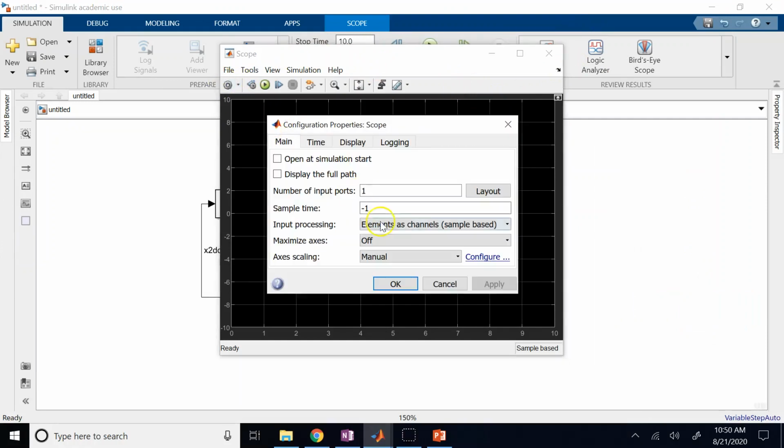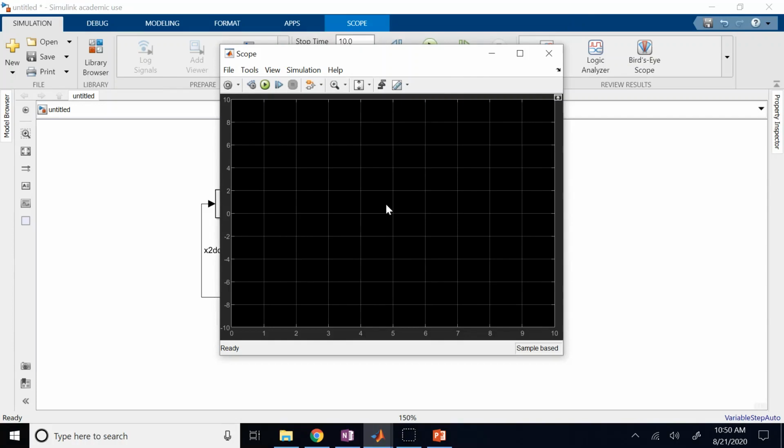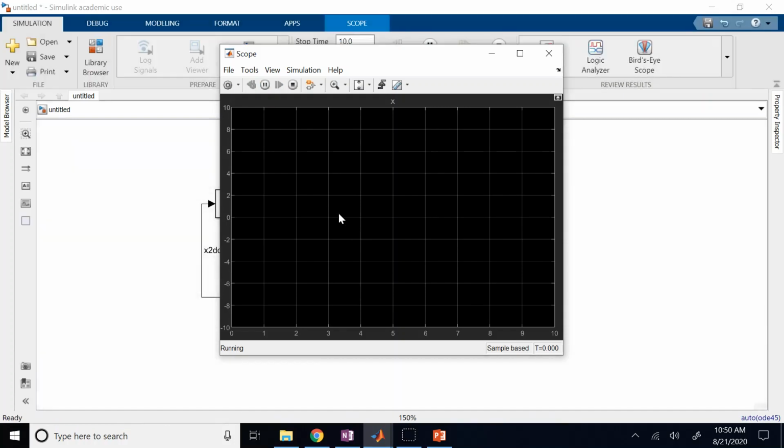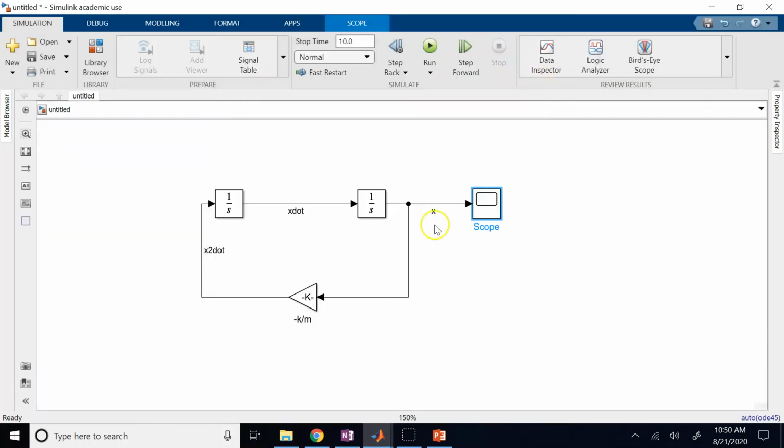Okay, and then I go here and make sure I will get a smooth plot. So I increase my sample time from -1, which Katia, sorry, I'm teaching so many software, I'm just messed up. MATLAB decides, I will tell it every 10 milliseconds. And now let's go here. Right, so this is what? This is going to be x versus t, but that's not what we want, right? Sustained oscillation. What we want is we plot x versus x dot.